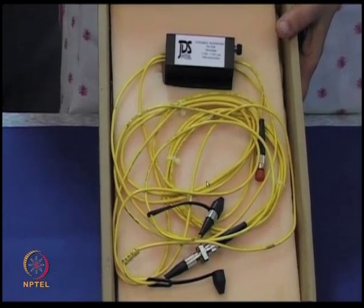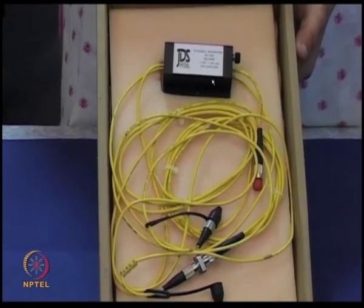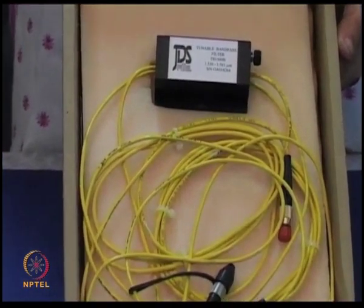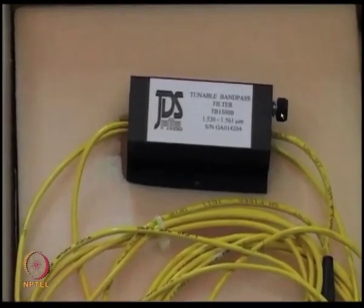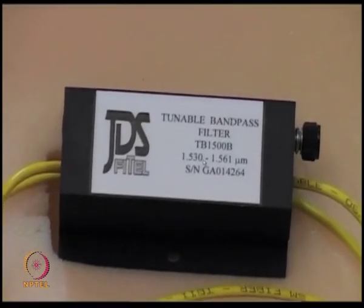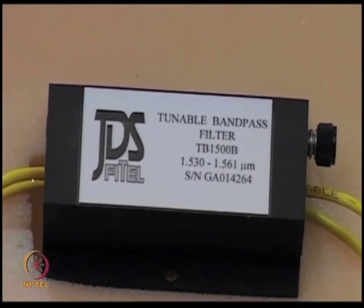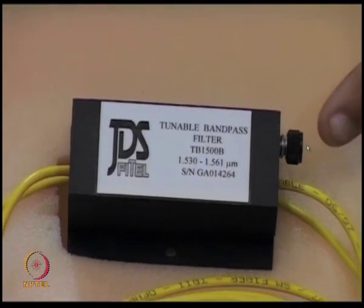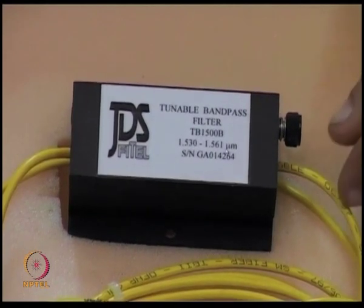This is another device which is a tunable band pass optical filter. So, you see here there is a small knob. When this knob is turned, the tuning frequency of the filter changes. So, if you are getting a broadband light, then a selective wavelength can be chosen by tuning this knob, and this filter works in a wavelength band of 1530 nanometer to 1560 nanometer.